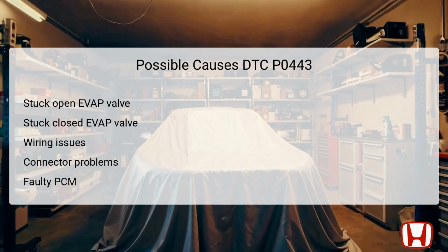Lastly, a malfunctioning PCM, powertrain control module, could misinterpret signals or fail to control the valve correctly, which would also prompt the DTC to trigger. Analyzing these causes systematically will be key to diagnosing the issue.